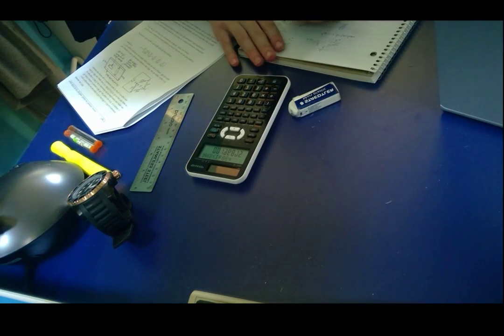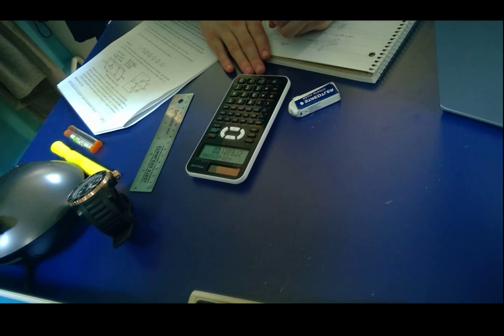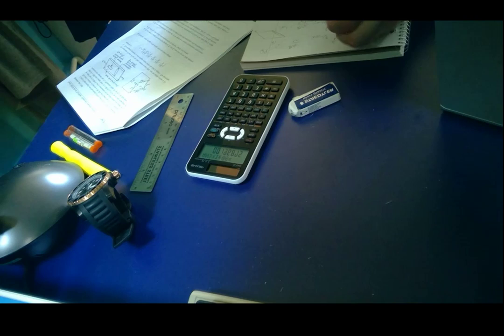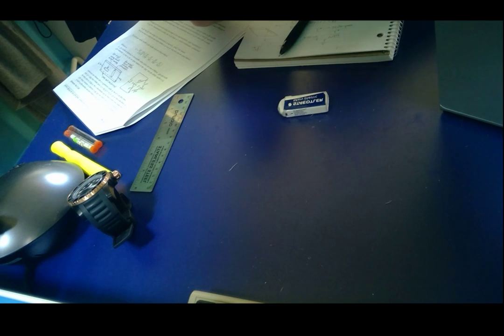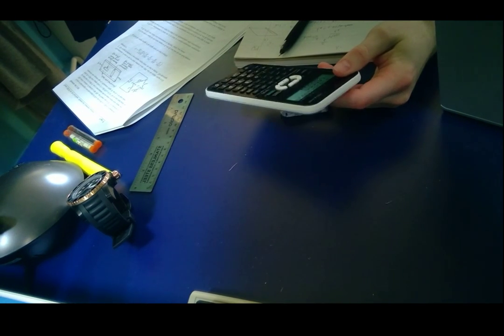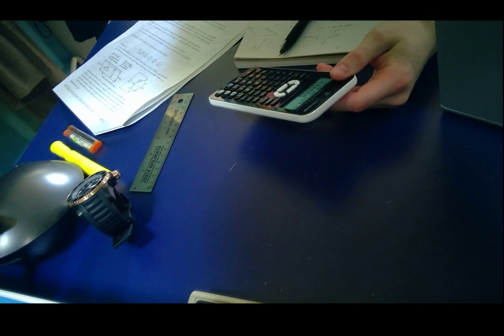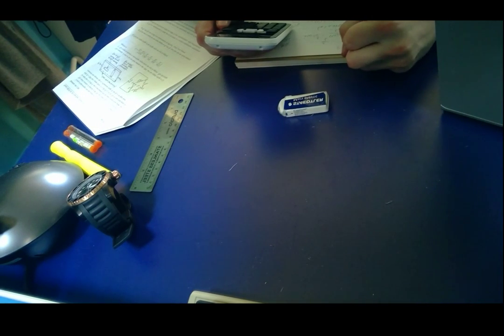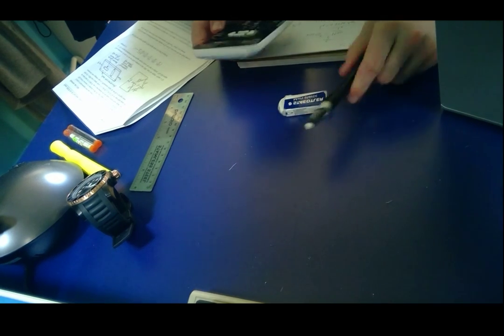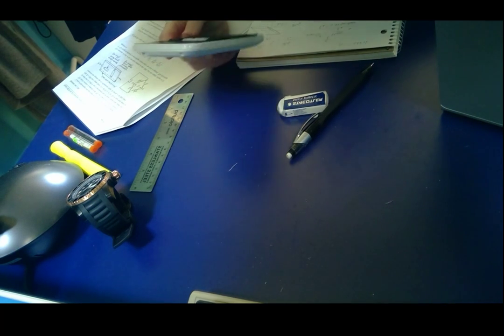So the axial strain is going to be on the cut area. And so I will redo these calculations using this new input. Thank you very much. A is going to be 0.001 times 0.02. Is it that way? I'm pretty sure it is. I hope it is. So that's the area, 0.00002. 50,000 divided by that. So that's the thing, divided by 200, E minus 9.